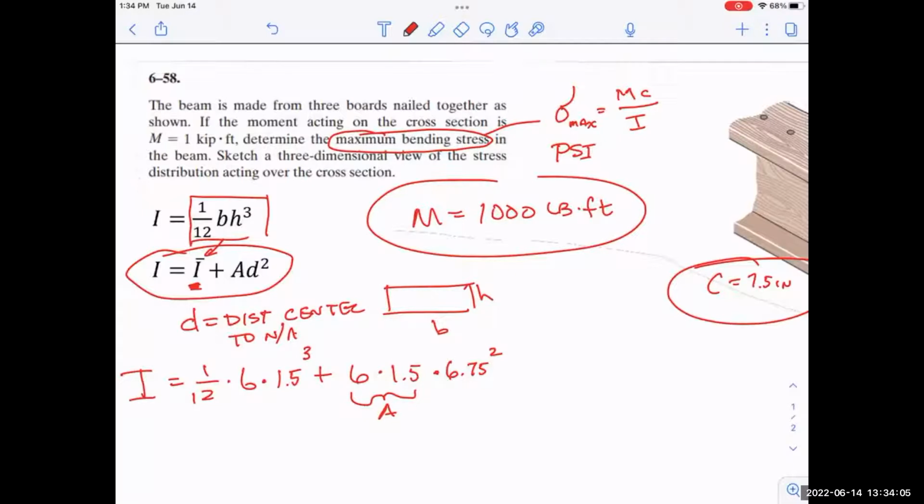And that's why you saw in those I-beams out of the factory, the inner part of that was like nothing. There was hardly any structure to it at all. And they said, oh yeah, you can punch holes in it. It doesn't even matter, because its purpose is just to keep the top and the bottom apart. As long as you haven't punched so many holes that the top and the bottom can move together, fine, because they're doing all the work. That distance out there, extremely important.